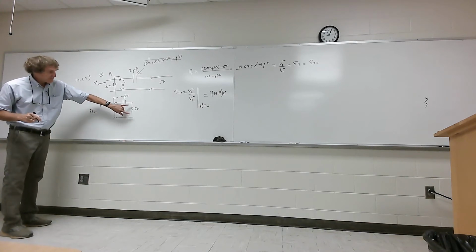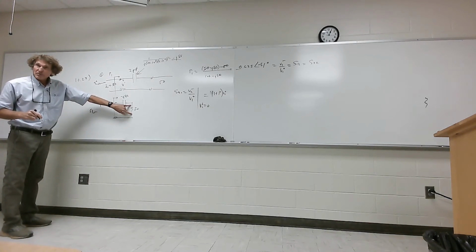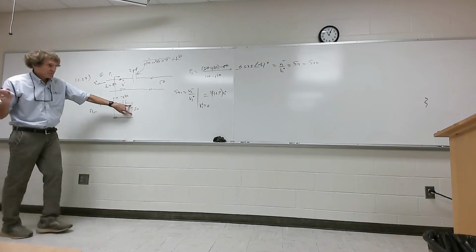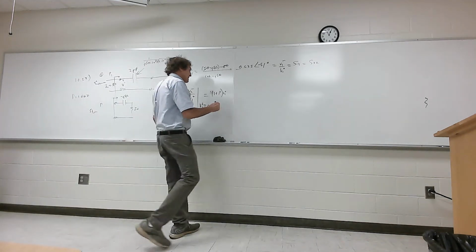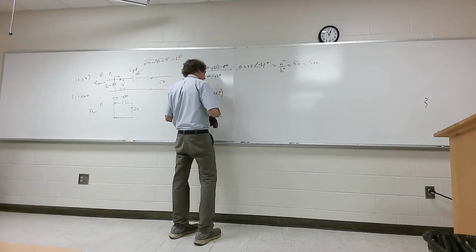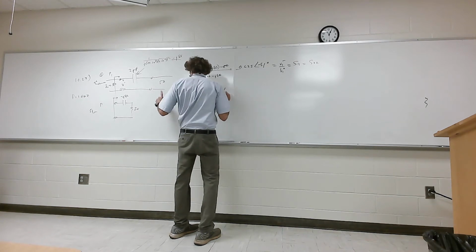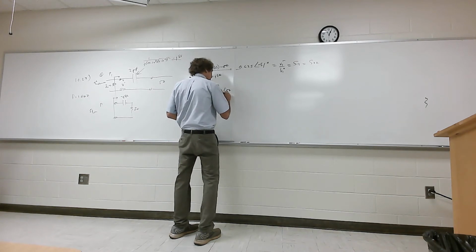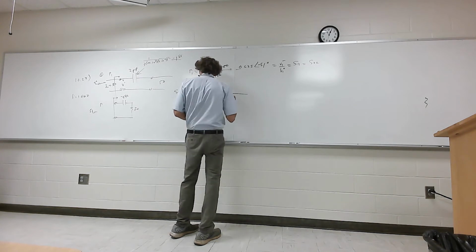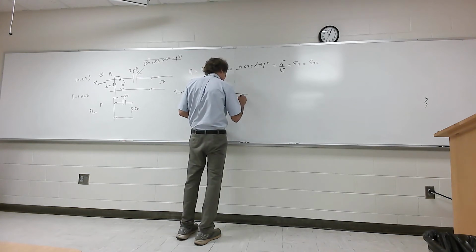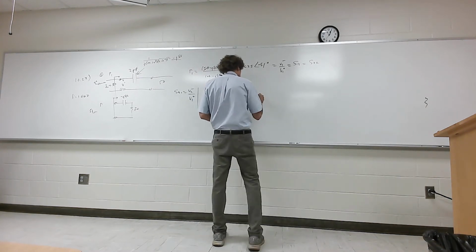Now I have to find the amount of voltage developed there. That would be on port 2, and it's leaving port 2. Y'all follow me? That's just going to be simple voltage division. Isn't that right? So I'm going to take that, and I'm not even going to put the V plus because it's going to go away. It's just going to be 50 over 50 minus J80.